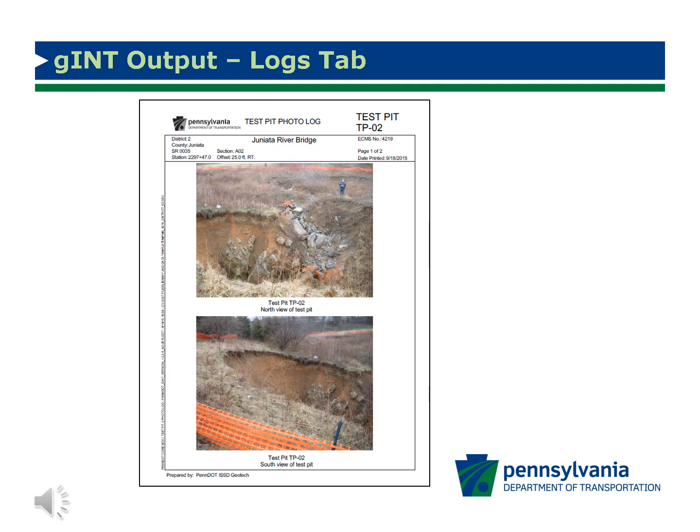To create the desired Core Box Test Pit Photo Log, click on the Output tab, then click on the Logs tab and select the desired boreholes, the preferred report. Click on the Export to File location and select the file name and folder and click on Save.